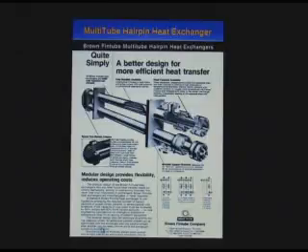In order to pull a bundle, you take this cover off. You open up this cover here. There's a split ring in there, which then allows you to extract the bundle out of the shell toward this head direction. These units can be stacked as shown here. They can be obtained in multiple alloys and in high pressure designs. So they're a good alternate when you're looking at a relatively small exchanger.